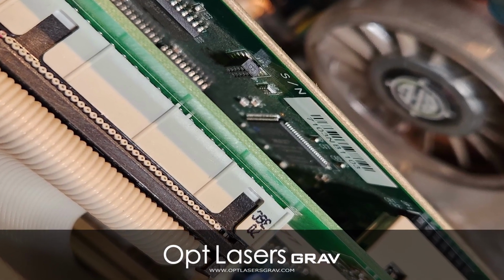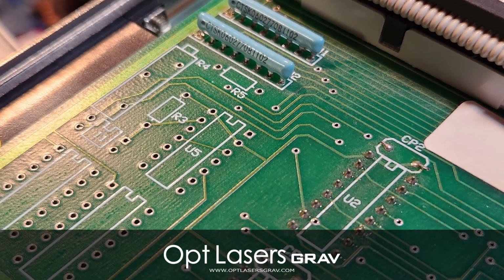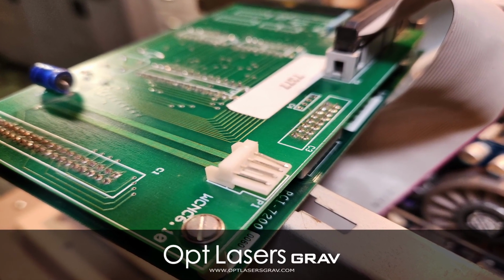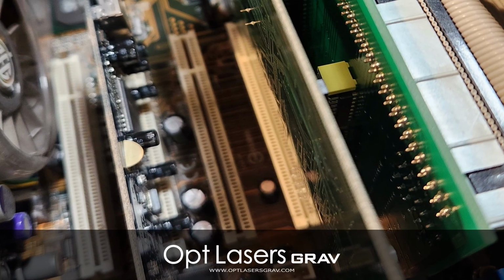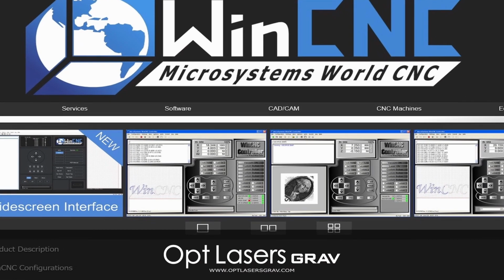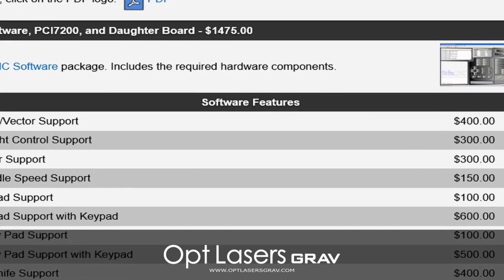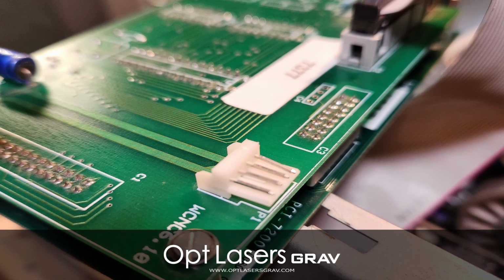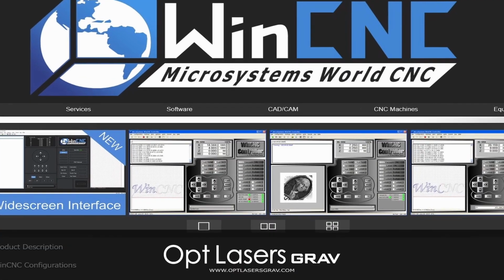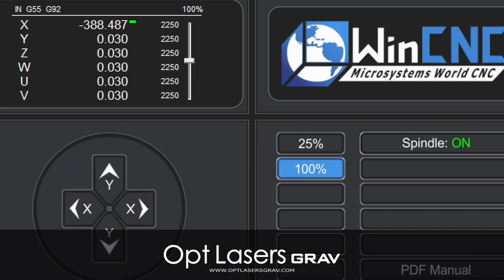The hardware includes a PCI card and a daughter board, which are installed inside the associated PC. The PCI card is a 64-bit high-speed digital I/O device, and the daughter board is a small circuit board which adds a high-speed microprocessor for pulse buffering. Both items are required to run WinCNC. Additionally, this control system requires supplemental software modules to unlock specific functions such as laser and spindle control. This combination of software and hardware that comes with WinCNC will not produce control signal without the appropriate module installed.